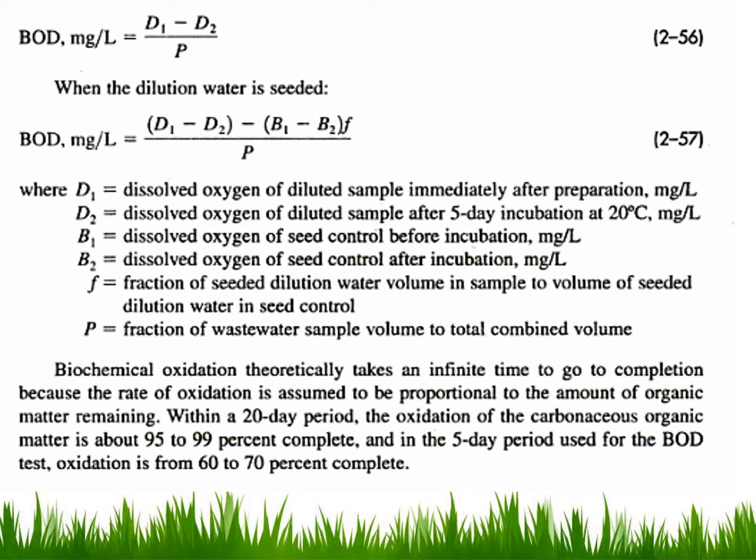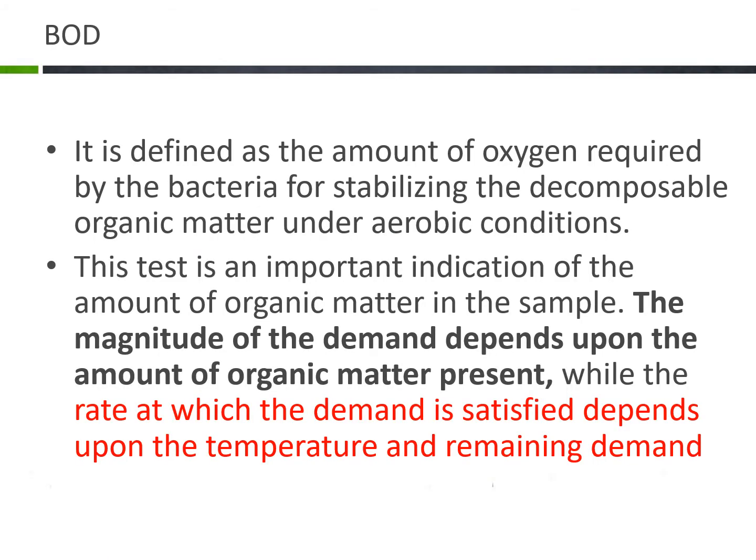Within a 20-day period, the oxidation of carbonaceous organic matter is about 95 to 99% complete, and in the 5-day period used for the BOD test, oxidation is around 60 to 70% complete. That's the summary of the BOD. Again, it's the definition. Go through it, please.